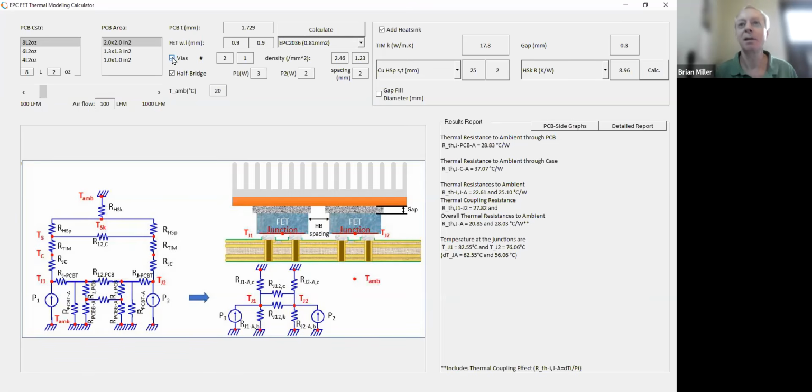And in-pad vias. So what if you say, okay, if your particular design would really rather not have those, I'm going to click this button. It didn't work previously. It's a beta tool, but I'm going to try it anyway. So we're at 82.5 degrees. And oh, it did work. Okay, great. So it goes up to 91 point, basically 92 degrees. So that's saying, okay, without vias and pads and a heat sink, what happens? And you can keep on using this type of thing.